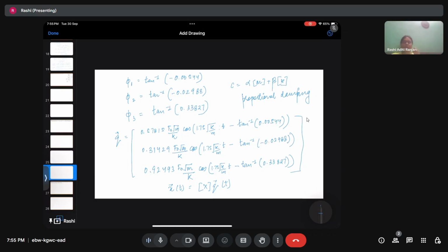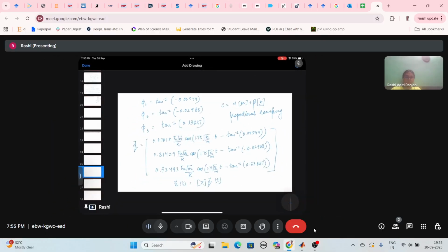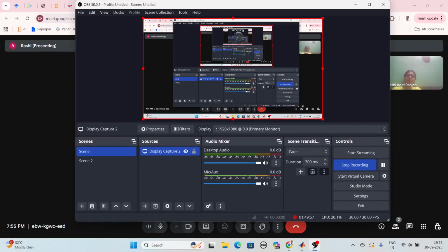Anyways, for a damped and a forced system, mostly the system response is going to be dependent upon the damped frequency only. So we should not be concerned much more on modal frequency and anything. But then, in order to know the internal behavior of the system, it is important to know the natural frequency, and then the modal analysis is definitely important in order to find out these modal frequencies or the natural frequencies, right? So that if we know, then only we are going to avoid it.